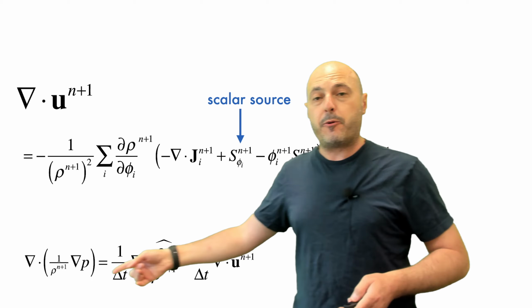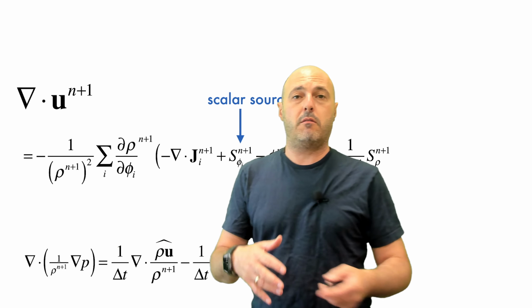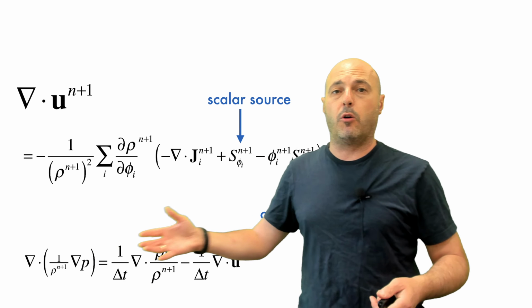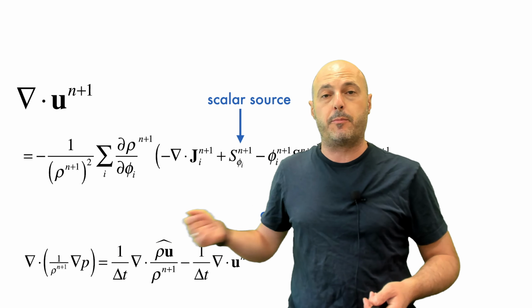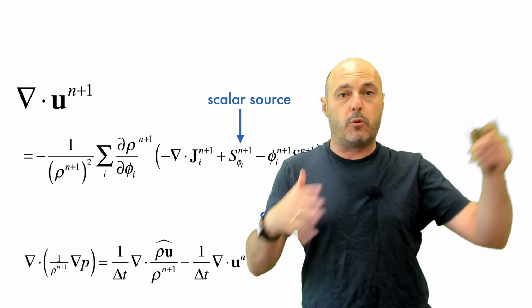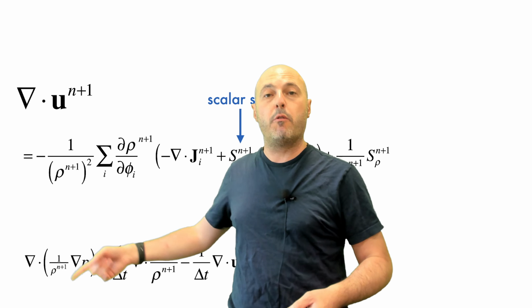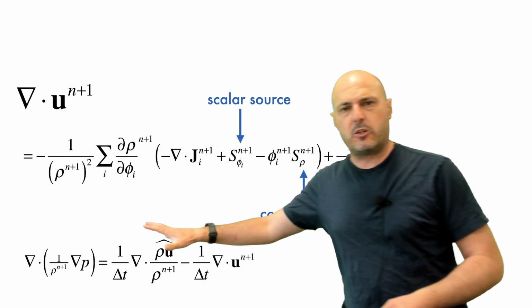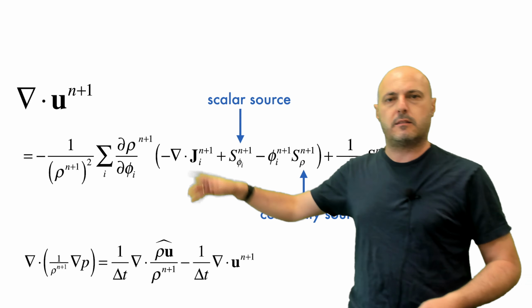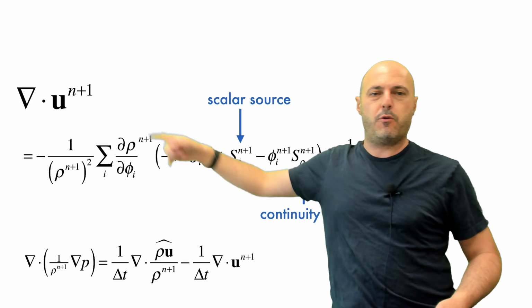And then now for the pressure, if you've done CFD and constant density flows, you would have a Laplacian over here of the pressure, just del squared P equals something. Whereas now you have density variation, a variable coefficient Poisson equation for the pressure, and it has this nasty right-hand side where you can just plug in div u and put it over here.